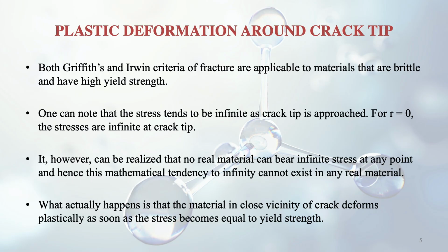What actually happens is that the material in the close vicinity of the crack deforms plastically, like you have learnt in the previous sessions about plastic phenomena. Up to the yield point, the material can come back to its original position after deformation, but after the yield point it becomes plastic, meaning it cannot come back to its original position, and it will retain a certain amount of deformation. So I am reminding you of that plasticity here. That's what happens, and so there is no infinite stress.